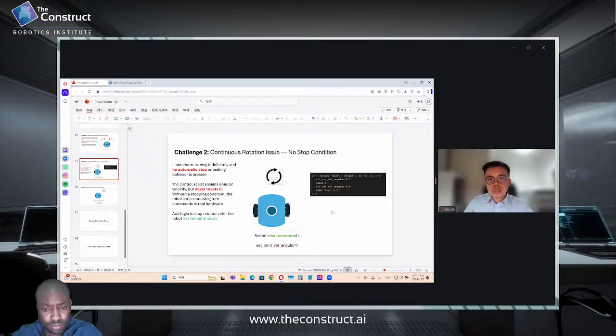The first time I didn't set it to 0.0, and I found the robot would receive this command and keep turning the 0.7 angle again and again. So I set the command to make sure it only turns once, just a 0.7 angle, and then stops. Then don't do any further, just wait for the other script to do the next actions. And did this work for you as close to real time as possible? Yes, in real time I also do it here.